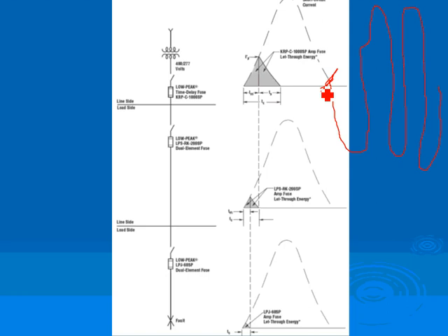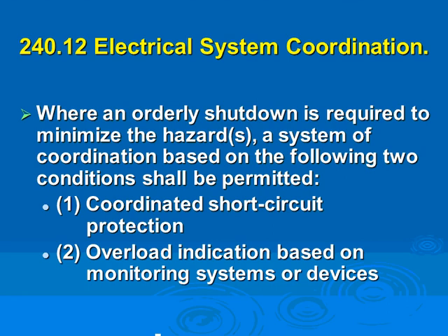So if you put a couple of them here, you can see how the energy is limited all the way down if you have a short circuit right at this level. So it's all about you. Is your equipment so important, like a VFD, soft start, or a UPS, that you really need to protect it so you can reuse it, or it's not? So, any comments, guys? Any questions? So that's your type 1, type 2 protection. Both of them will meet the NEC code book.